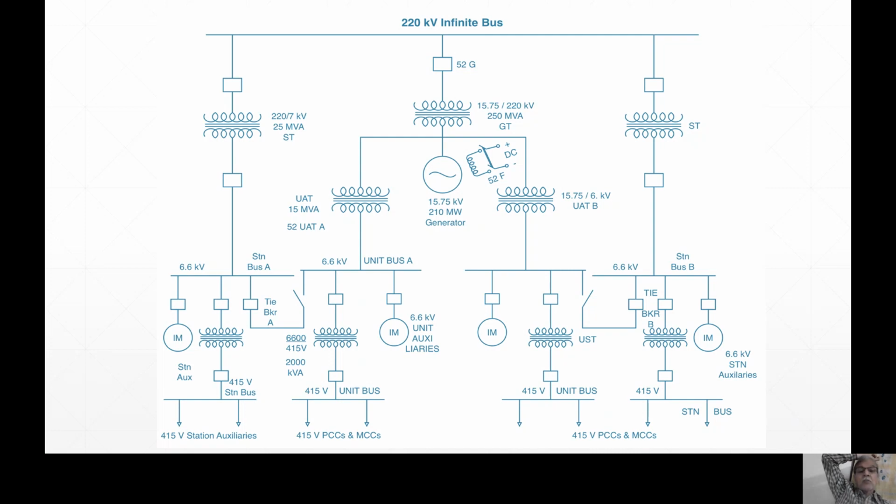There at the top there is the boiler drum and the boiler feed pump is at the ground floor. It serves water to the boiler drum at 170 kg per centimeter square, at roughly 275 degrees. It is water, my dear friends. At 100 degrees, water turns to steam. But here, because it is 170 kg per centimeter square, it is yet water.